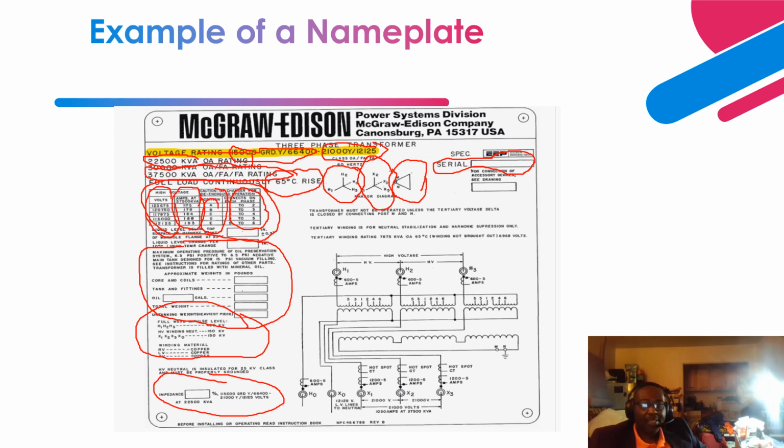Okay. Next it's the winding arrangement. As you can see over here, the high voltage side is designated by H1, H2, H3. So H1 is phase A, H2 is phase B, H3 is phase C. This particular transformer has only one bushing located below the top compartment. This is where basically the bushings go through. So this is a typical bushing type current transformer, rated at 600:5.